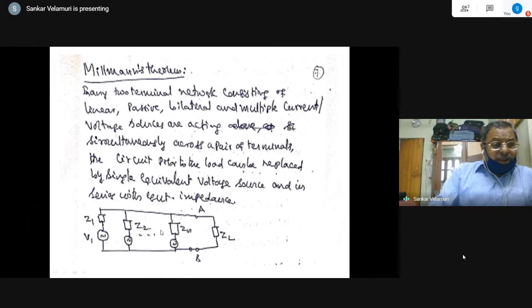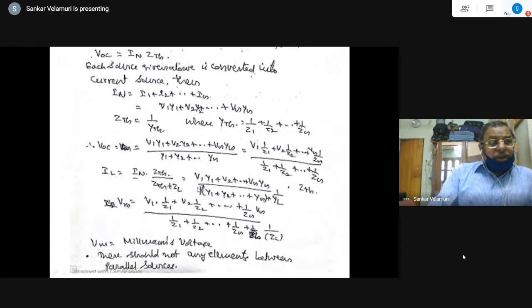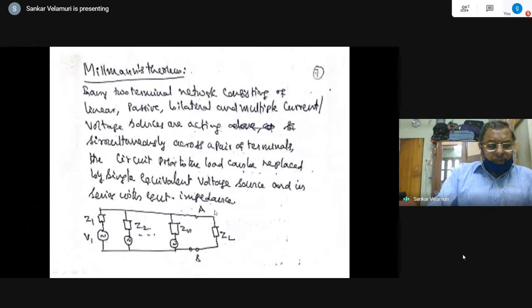In parallel with that, Thevenin's equivalent impedance for this particular row only is Z1. So V1 in parallel with Z1 becomes transformed to I1 in parallel with Z1. Similarly, I2 in parallel with Z2 are the shunt impedances which we are taking. So the total shunt, and that is how you have to imagine, if you recall that derivation, because it looks like a derivation, but it's the equivalent circuit of that.